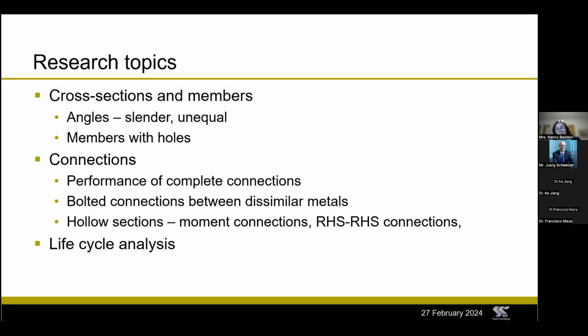And for hollow sections, the guidance in AISC 370 is somewhat limited. Topics such as moment connections, plate to hollow sections, and rectangular hollow section connections are missing. These are all the types of connections where behavior is governed by deformation rather than strength.